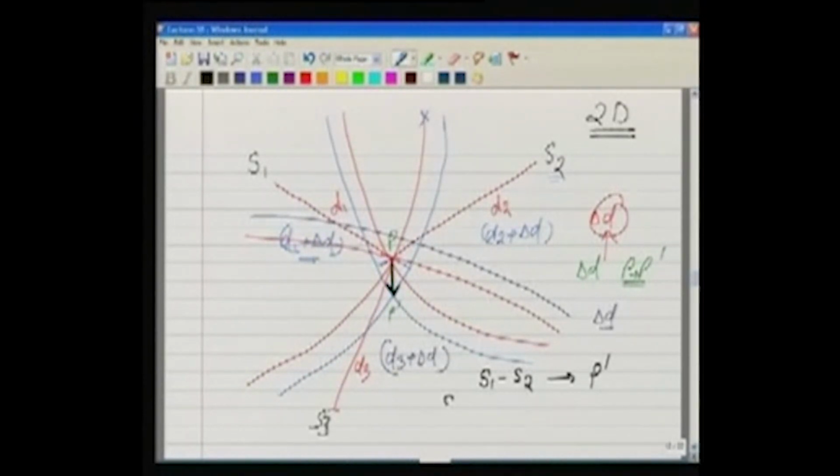Now when we are using S1, S2 and S3, are we getting any single position? No, because what we are getting as the position is now this triangle, which we call the triangle of error. That means our point has to be somewhere in this triangle. Now, if we observe this triangle, we will find the actual position is the centroid of this triangle.